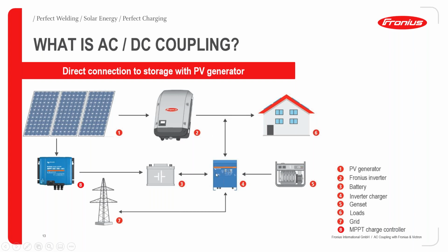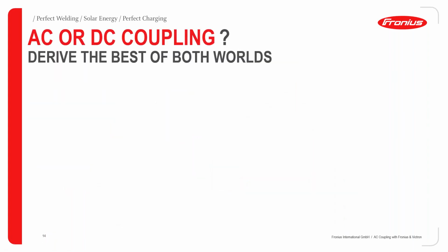and then we can now have power back into the system. Because one thing to note here is that the PV inverter, like the name implies, or also called the grid inverter, actually depends on the grid to function, meaning that it uses the grid as its control voltage, while the Victron inverter uses the DC voltage as its control signal or control voltage. Of course, my Victron colleagues will be shedding more light on this.